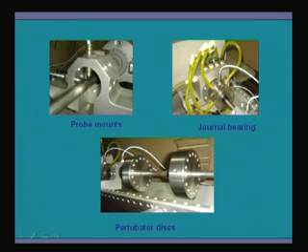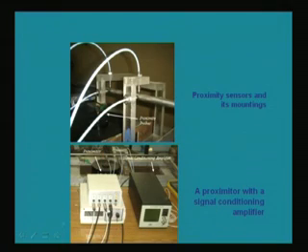This is the close view of the disc. You can see that there are holes on that. We can put some kind of known unbalanced force in that to simulate some kind of force vibration in the machinery. This is a close view of the proximity stand, vertical and horizontal, measuring the vibration of a beam. These are the amplifiers, because these signals are generated in voltage form, they have to be amplified, and then we can display them.